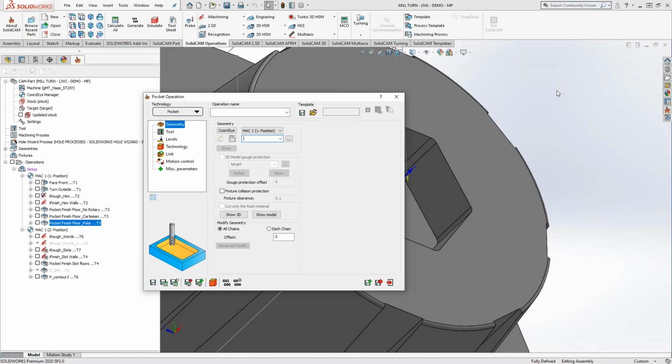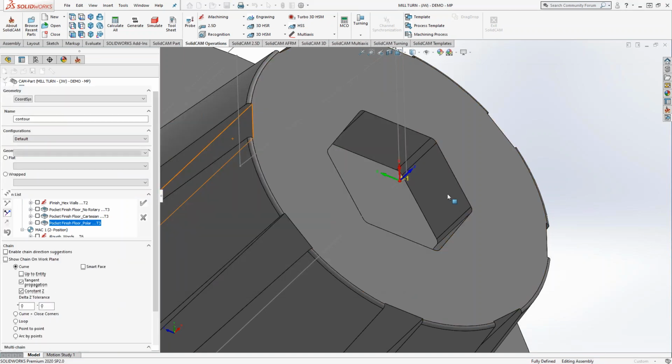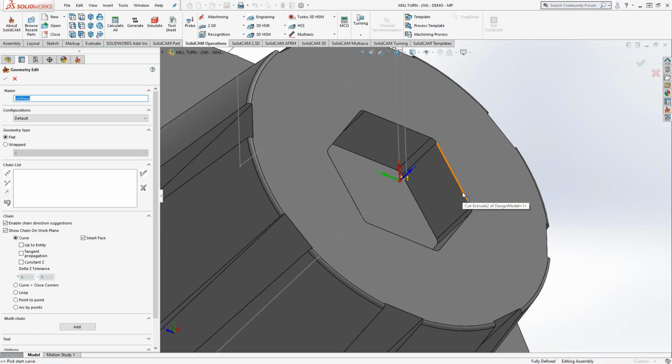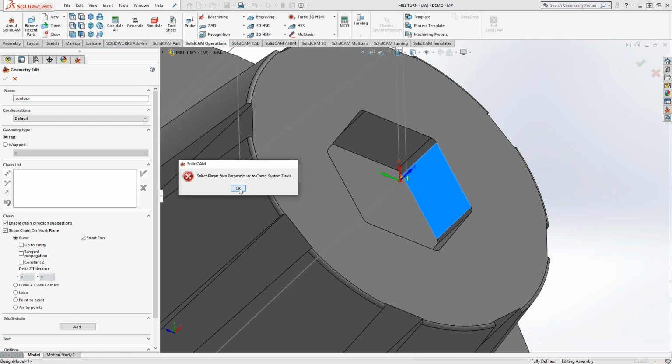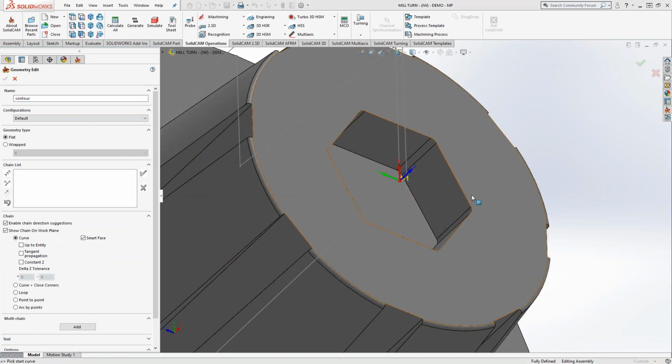Because remember, when you get into the toolpath, whether it's profile or pocket, you are choosing a depth, an upper level and a lower level, or an upper level and a pocket depth or a profile depth. So it eventually will be consistent. Go ahead and chain what you were just working on, chaining, going up and down there, and then we'll turn on the show working plane. I already have it on, so let's see what happens. That may help out. It's not actually getting projected to the tool plane there, but let's see what happens.